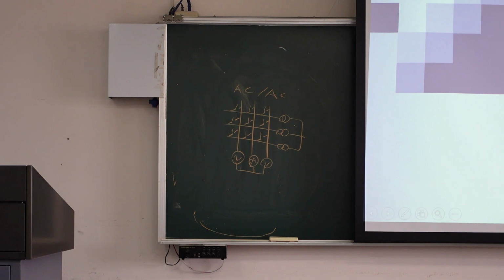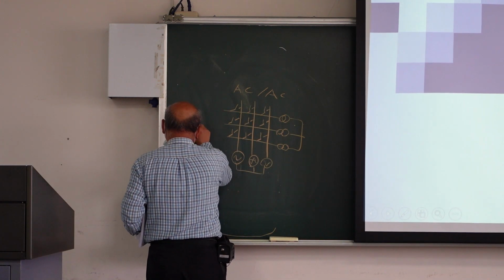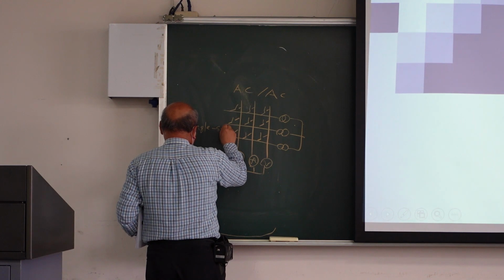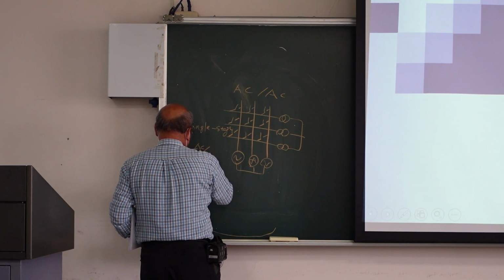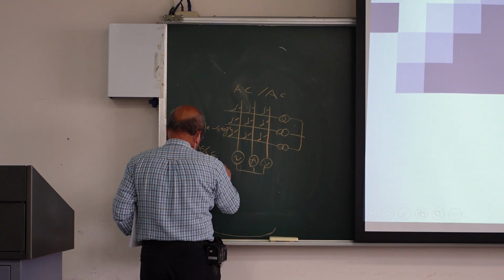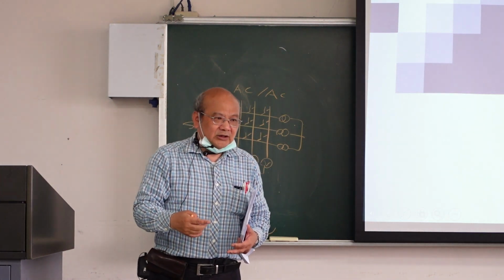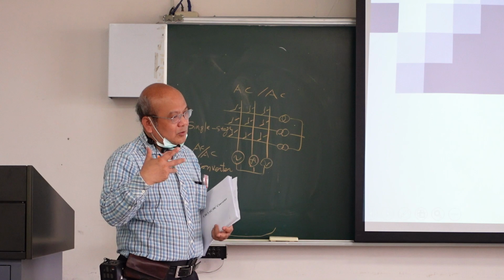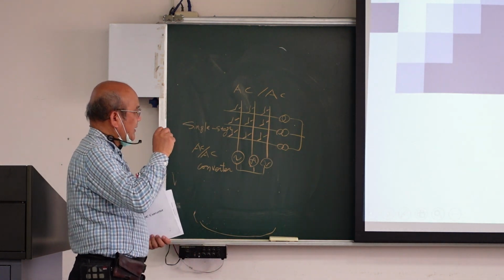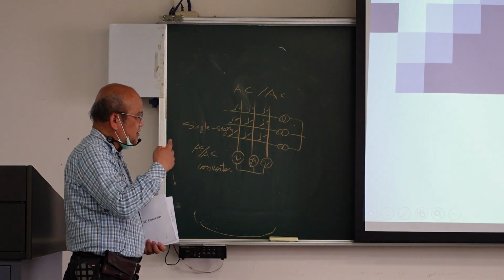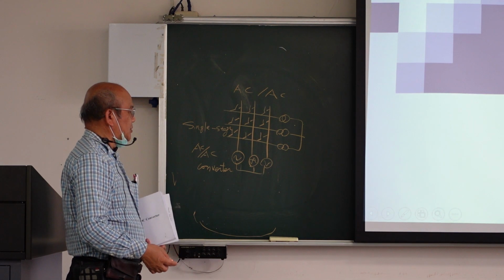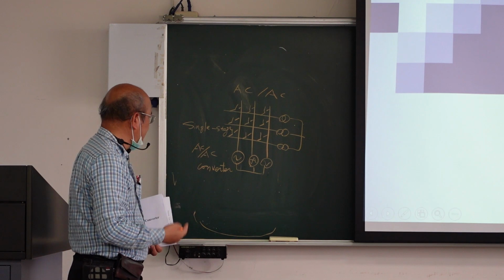So do you need a single-stage or 2-stage AC-AC converter? 1 stage, right? So the idea should be 1 stage. So we can say this is a single-stage AC-AC converter. The idea is very simple, and it is reasonable. We do not like 2 stages. We prefer 1 stage, and we can get better efficiency. We can get a simplified topology, and the price should be reduced.